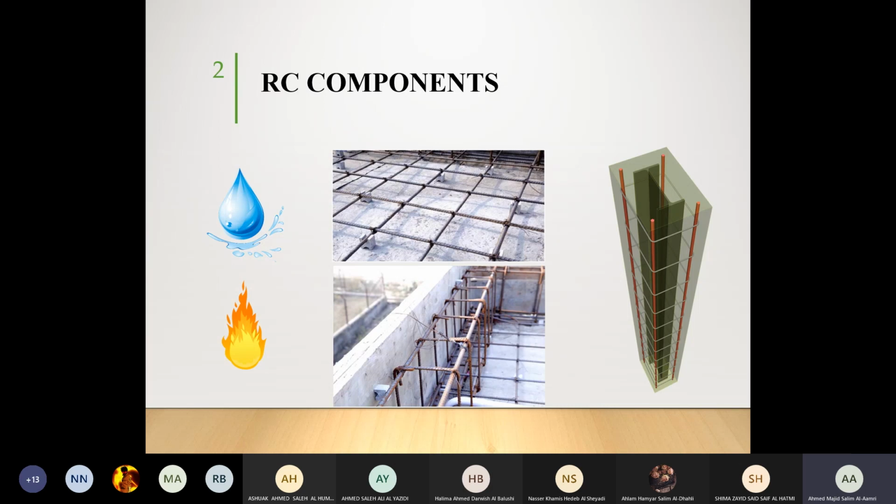But this paint withstands for hours, right? Yeah, of course. Even if you are designing for concrete, you are designing it for certain hours. This cover will stand for certain hours. These hours are sufficient for you to be evacuated. It means that when I design my building for 2 hours or 3 hours, for example, if I'm designing my house, I require 1 hour of fire resistance. Why? Because if you are staying in your house, it will be easy for you to go outside. You don't require a lot of time to be evacuated.